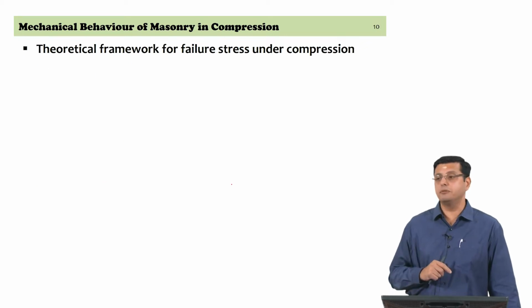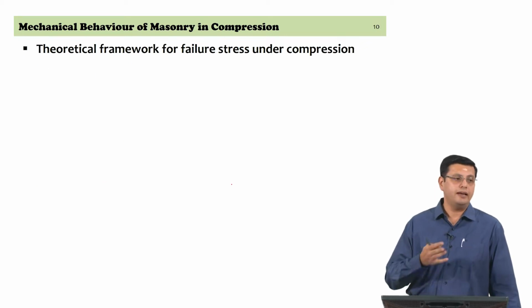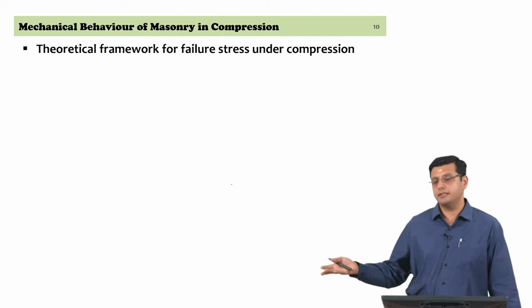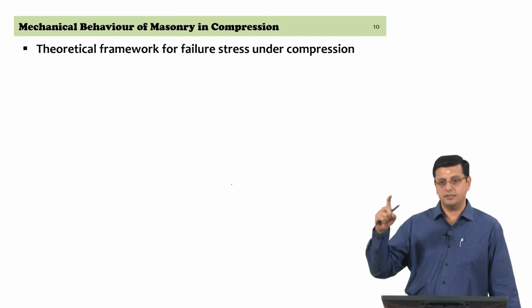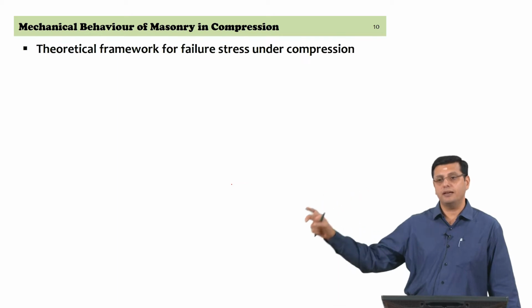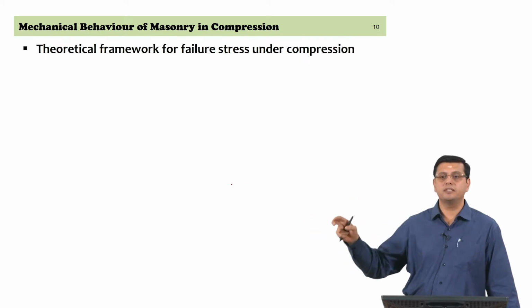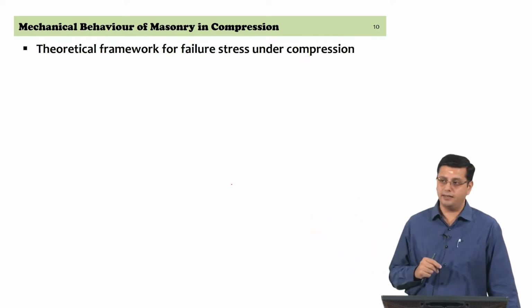Now, let us examine mortar and what is happening to mortar, and we understand that when we are doing a uniaxial compressive test on the mortar, it is under uniaxial compression, but in the prism under compression the mortar goes into a state of triaxial compression.